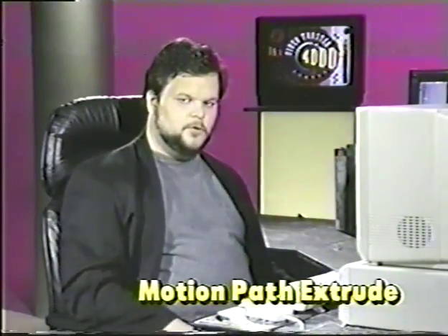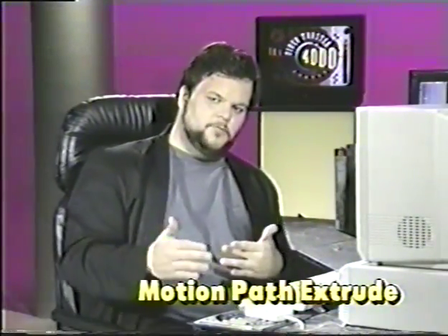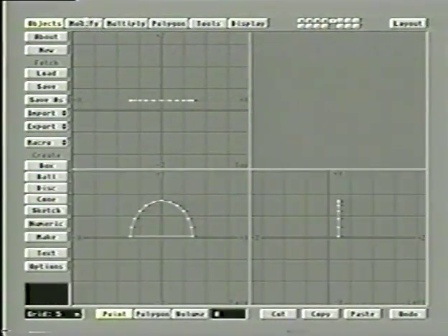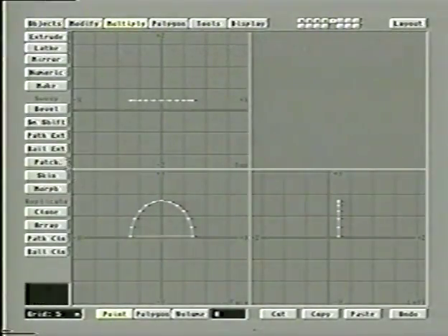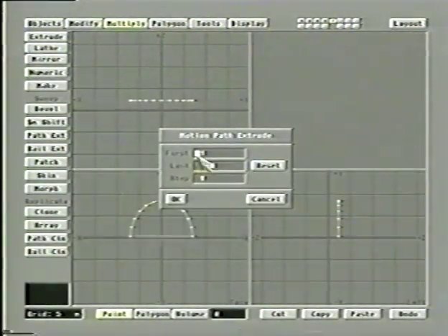We need it to follow the same path that the car is going on, though. And so to do this, we're going to use path extrude. Very, very similar to rail extrude in that it's doing an extrusion, but not necessarily straight back. With path extrude, though, it needs to pick a motion path, and it will move it along there. So let's just take our shape here. We'll go to the multiply menu, path extrude, pick a car motion, and it will come up and ask us,